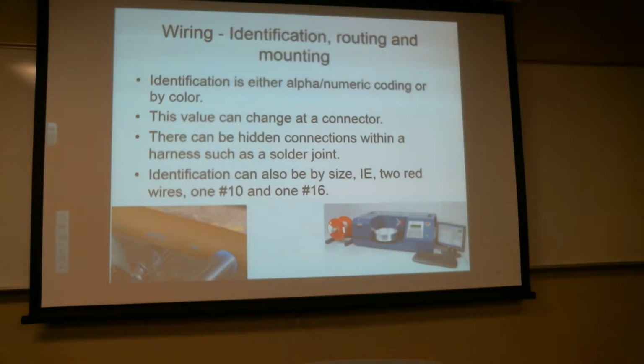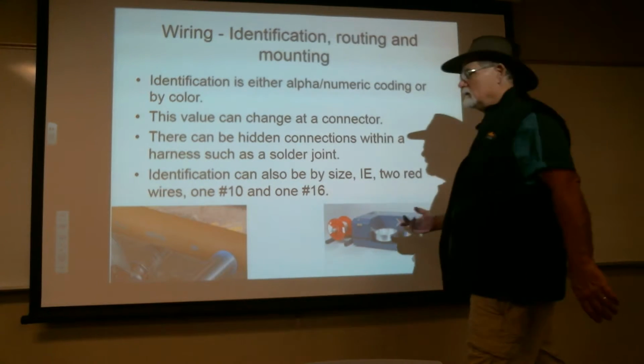Sometimes the identification process will include data about wire size. So in other words, if it uses 2 at the third character, it means it's a number 2, or some other cross reference that you don't necessarily know what it is, but it might be cross referenced in the initial index as it describes some things in the manual about how the wiring system works. So sometimes the actual part number or identification number of the wire gives you information above and beyond just what wire it is.